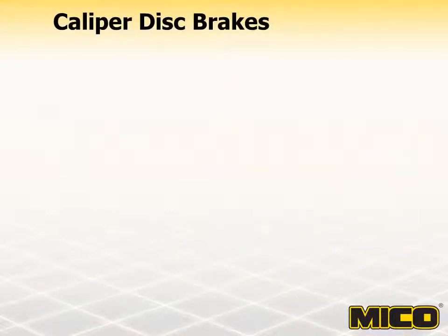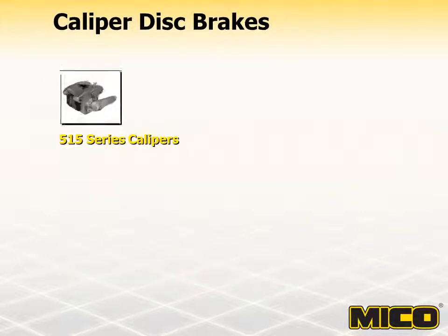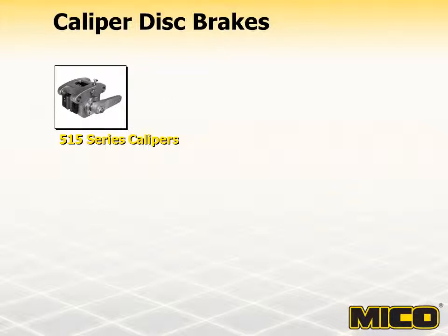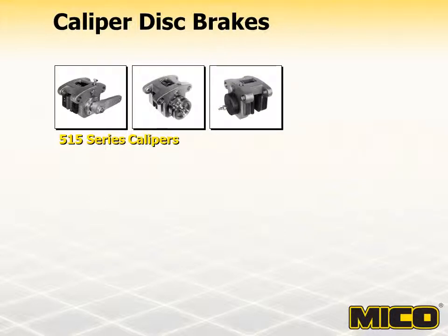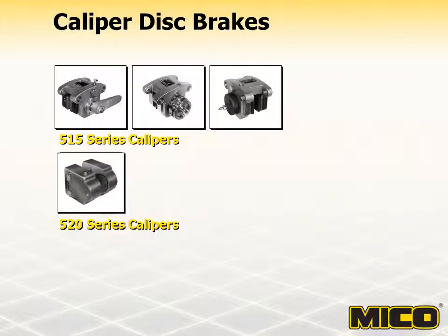There are three series of caliper brakes available from MICO: the 515 series, the 520 series, and the 530 series. 515 series brakes are available as mechanical apply, spring apply hydraulic release, and hydraulic apply. Although this series of caliper brakes is normally used for static braking applications, they could be used for limited dynamic braking applications also. 520 series brakes are all hydraulic apply.